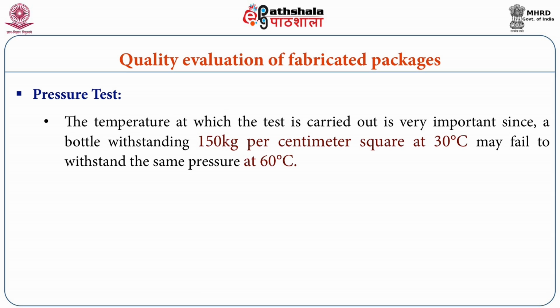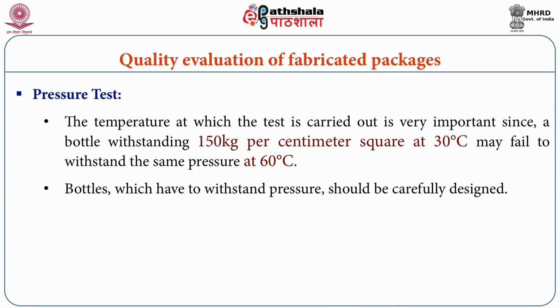The temperature at which the test is carried out is very important since the bottle that withstands 150 kg per centimeter square at 30 degree centigrade may fail to withstand the same pressure at 60 degree centigrade. Bottles which have to withstand pressure should be carefully designed.